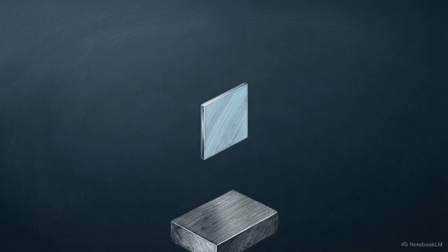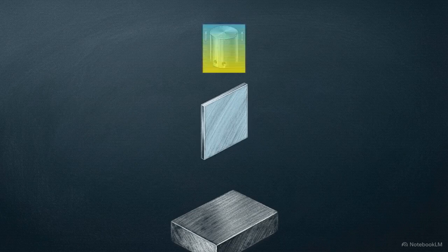The physical setup involves bonding a rigid pull tab directly to the surface of the coating, creating a mechanical interface for extraction. As the tab is pulled away from the substrate, we apply a stress map overlay. This represents a finite element method, or FEM, analysis, a computational tool used to predict how materials react to physical forces. The FEM reveals a major vulnerability: premature stress concentrations at the sharp edges of the specimen.